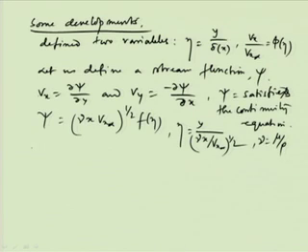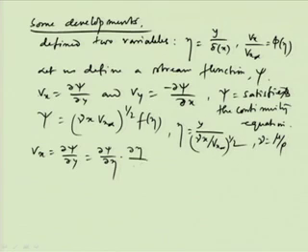So, what we get from here is Vx is equal to del psi by del y, and that is equal to del psi by del eta into del eta by del y. So, doing the differentiations, it can be obtained as Vx infinity into df by d eta, because f is a function of eta only, which is nothing but Vx infinity into f dash. Okay.